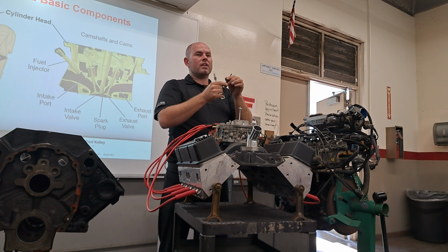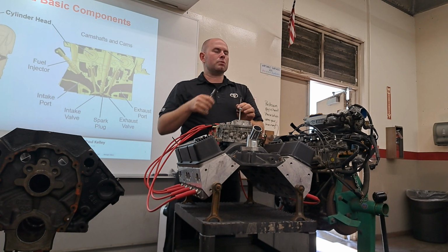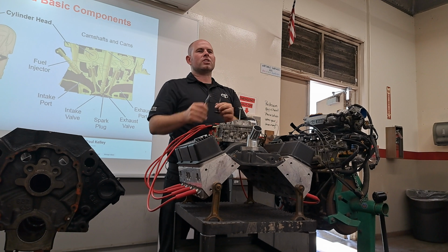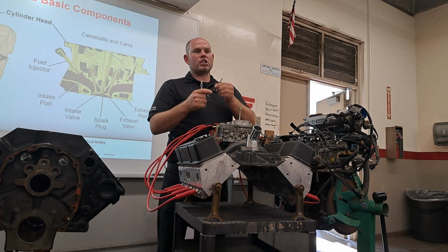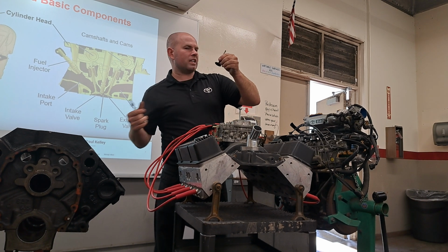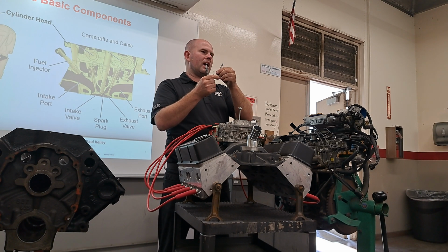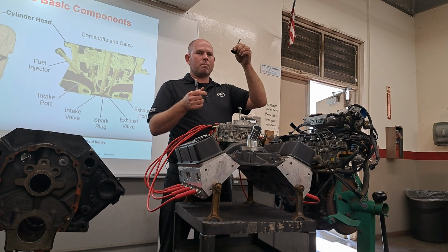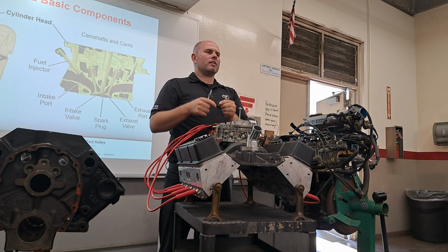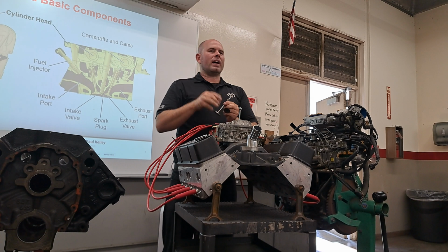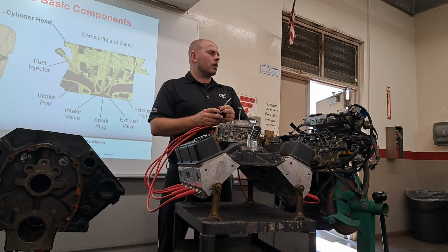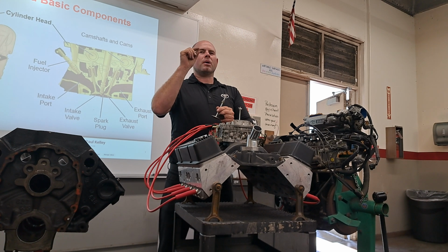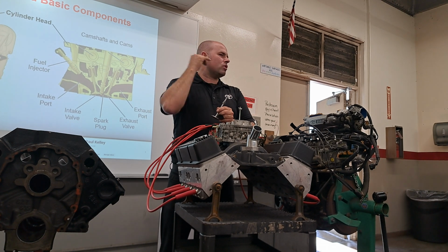So the valve clearance adjustment is not generally because your cam is wearing and now it has too much clearance. It's opposite. It's generally because your valve spring has been slamming the valve up into the head and it's recessing. It's called valve seat recession. It's beating its way up into the head and it starts to get tight. Now let's take it a step further. You had 7 thousandths and that's good. By the way, if you somehow ended up with 20, you'd probably hear a ticking sound, right? But if you're down under 7, you won't hear anything. You just feel like everything's fine.